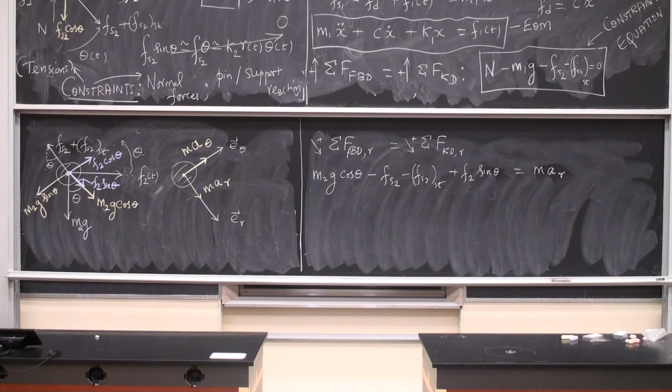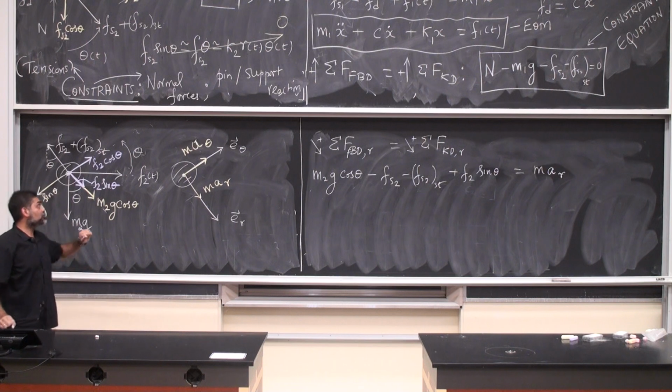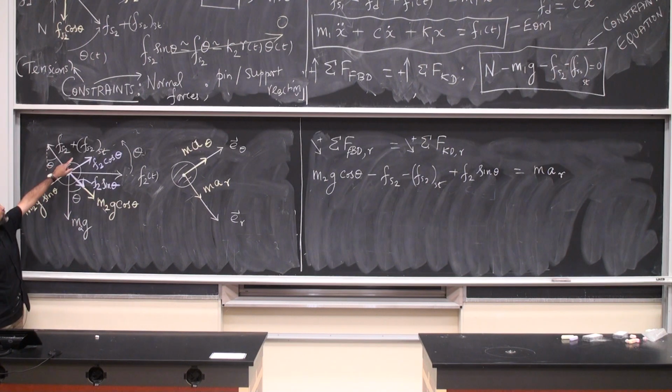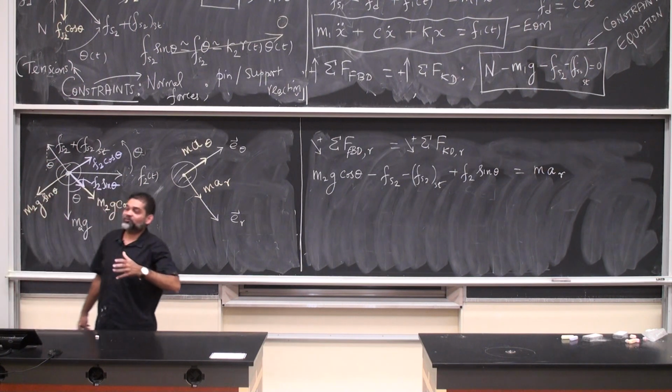Yes, Fs2 static. You can, but let us assume that more or less that's always going to be in the radial direction along the length of the spring. So that's a component that's carried through. If you really want, you can break it up into components and you'll figure out that it's only this component along the radial direction that will cause anything. It will be Fs2 static times cosine theta. The one along the transverse will be Fs2 static times sine theta. And that will be very small.